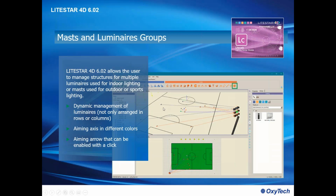Another feature is that over here you have the example of an aiming. The aiming is characterized by a line, and this line ends with an arrow. You can activate the aiming simply by clicking on the arrow. It is not necessary, like before, to select the luminaires and then come down to find the arrow and the aiming. It is automatically activated from here.